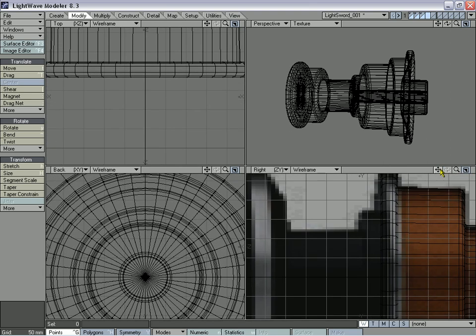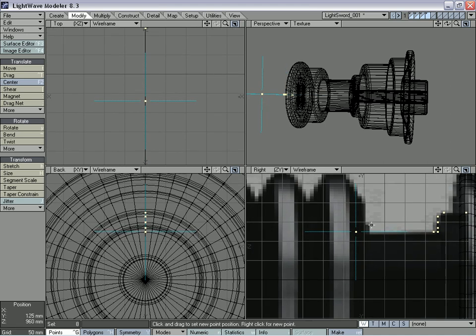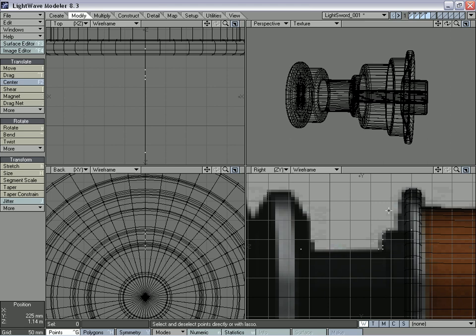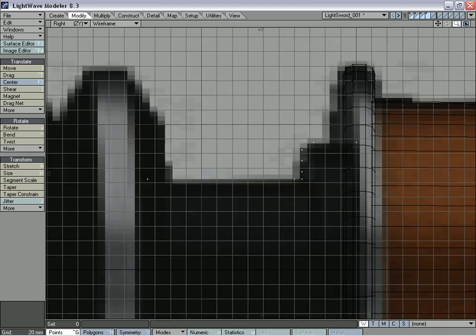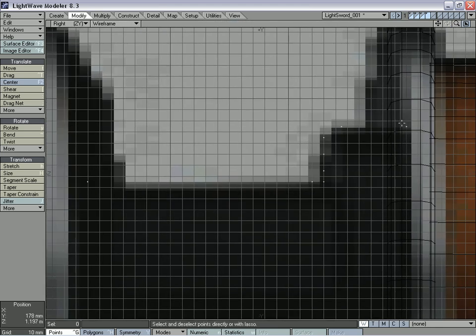And this is pretty much the same as section 2. So we're going to Shift plus key, create our points, and go in just a little bit into the previous section. And when you get to these rings, this is going to be the next section here. So we can just go into that just a little. Undo. And select those new points. 0 on the numeric to expand the view. And this is going to be straight.